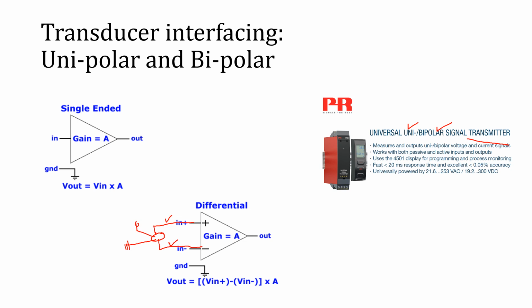So till now what we have discussed is that transducer interfacing is very important, since most of the time we come across resistive transducers, so we have discussed those examples. But if we have a capacitive-based transducer or an inductive-based transducer, even then we can go for bridges. You must have read about bridges which are based upon capacitance, like the De Sauty bridge, and inductive bridges in which we control the inductance of the circuit.